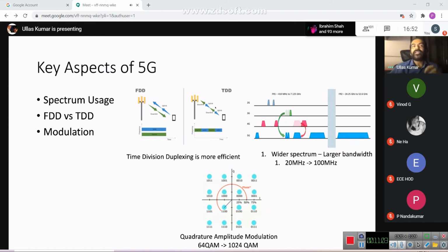Why is it done? To increase or maximize the channel usage. For example, if you were sending ones and zeros from one place to another, you could combine them. You could make combinations of, say, 4, so it becomes 00, 01, 10, 11, and then make a symbol and send it, so that the other side can get the symbol. Rather than sending significantly more bits, you can now reduce the number of bits and send more information.